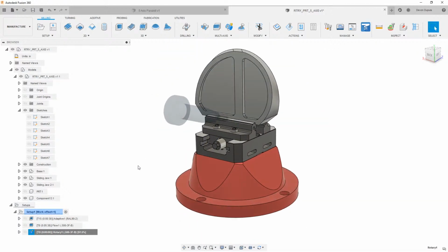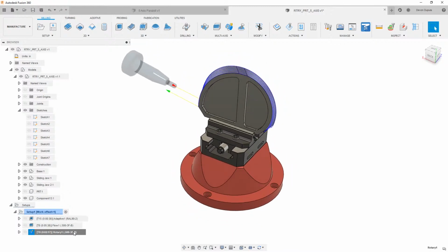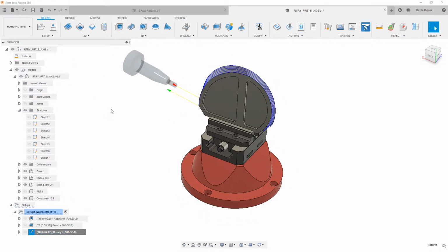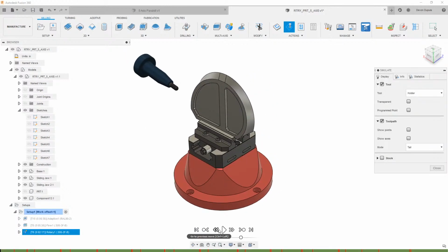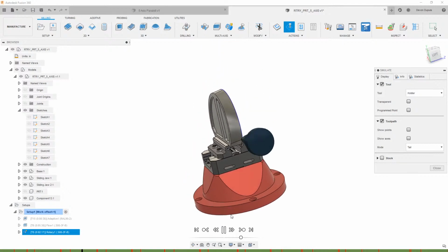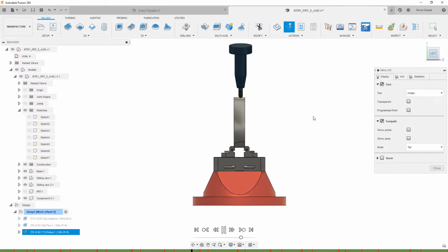Based on that origin and everything that I set up there, now we have a fairly smooth fourth axis toolpath on this, even though this could be on a fourth axis machine or a five axis machine. Now we're staying normal to that surface from the side, and we're not getting all that volumetric error with moving all of our rotaries at the same time.